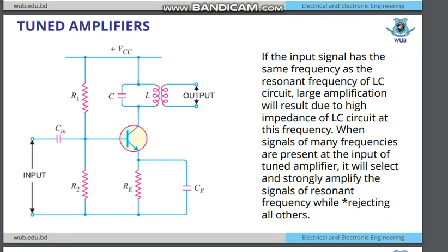In tuned frequency amplifiers, here is the basic tuned amplifier. As you can see, it is quite similar to what we previously taught about in the oscillators. There is really a tank circuit, but the output is not taken on the amplifier side; it is taken on the side of the tank circuit, the inductor, and that will be a tuned amplifier. So that is the difference.